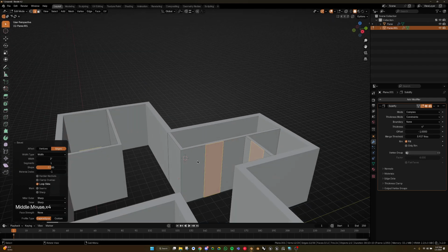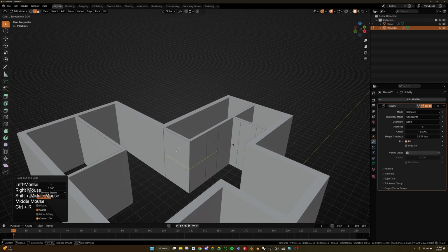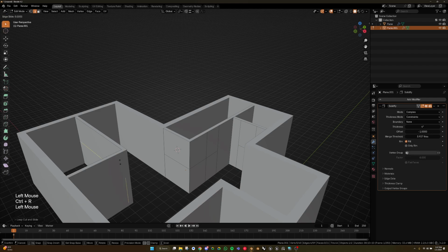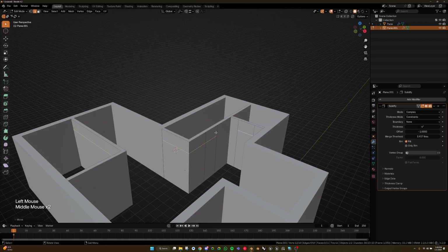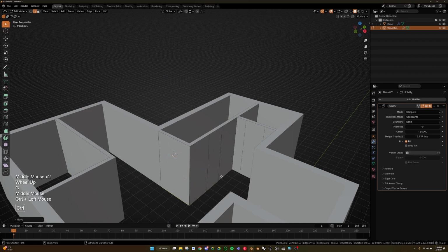And then if you want to have your height established, you can add a loop cut here, add a loop cut here. Remember, look at here. Control R. And then if you want to select this loop cut, remember, connected by quads, you hold Alt. I'm going to hold Shift as well, so I keep this selection. Click and click, and then I can move it up. But what if you want a certain distance from the ground? So what I like to do is have my snapping on, move it all the way to the base, and then move it up, right? So it's a point from here to here.